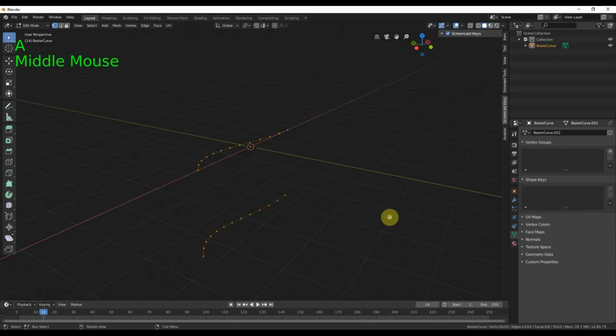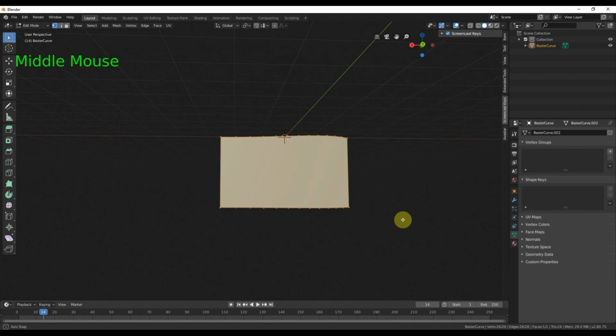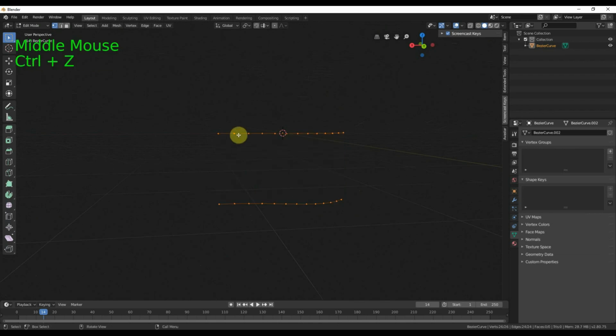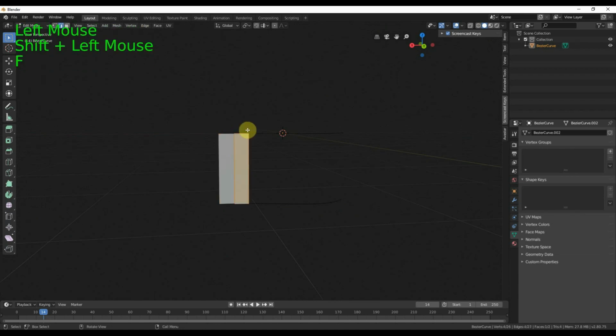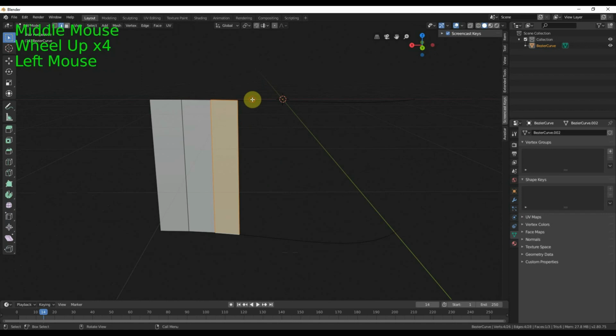And we'll select all. We could press F to create this face, but it is an end-on face. You see there's no vertices coming down it. It's more accurate to create our own faces. So for example, if I go to edge mode here, I select this first edge, and here I could press F to make that face and work my way down the curve. So we're getting a more accurate curve shape with quads.